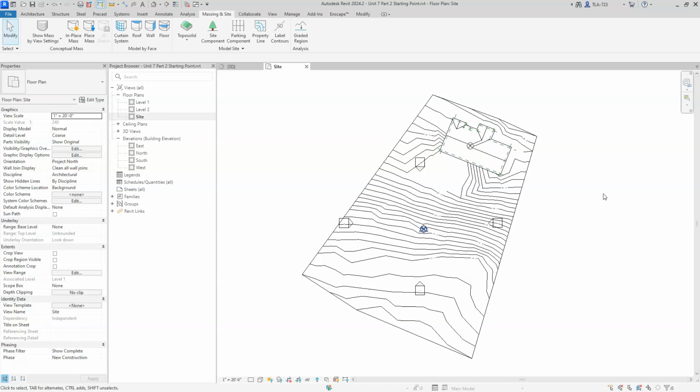have to draw one, you really need to know exactly the direction and the length of all of the legs of that property boundary. Now, that might be data that you've collected during surveying, or it might be data that you received from somebody. But if you ever have to reproduce it in Revit, you should be doing that according to the exact measurements and angles, so distance and angles of that property boundary. Now, I don't have that data, so for this demonstration, I'm going to be picking random points, and you can too, okay?